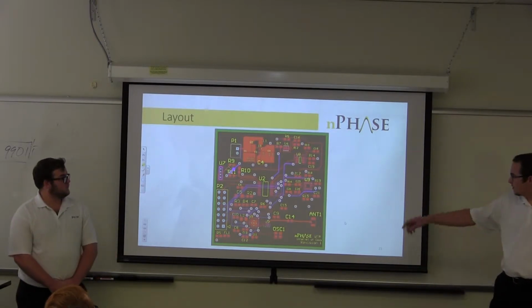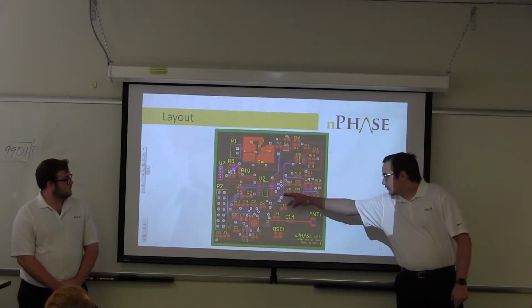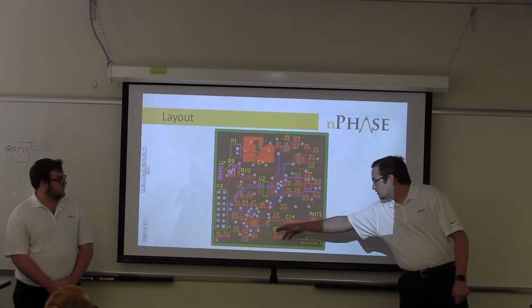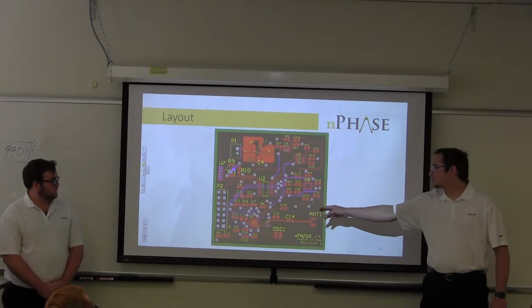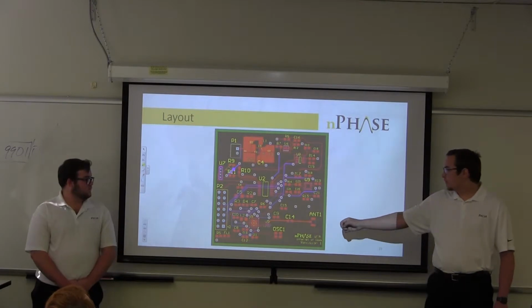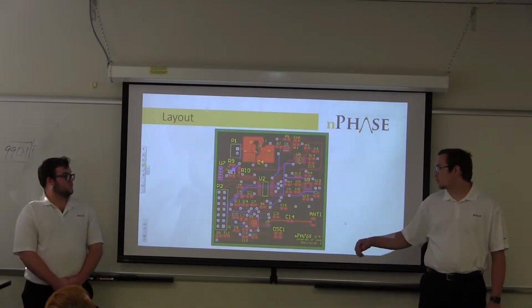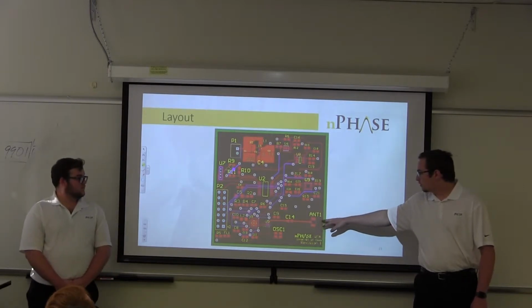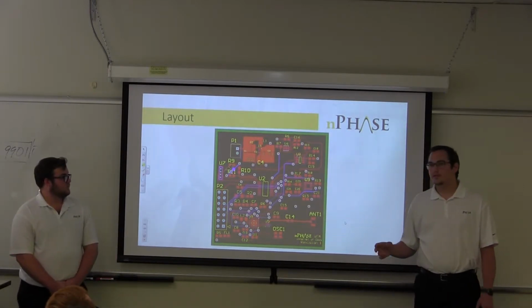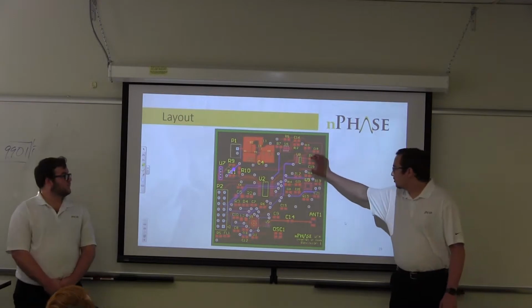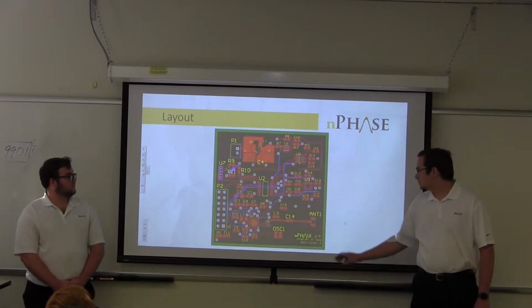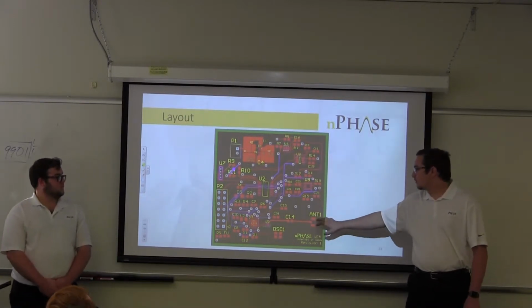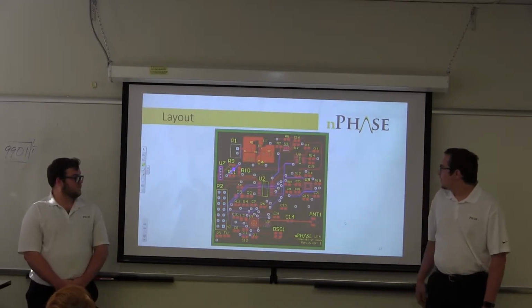And then U2 is our MSP430. This is our 1310, which goes through the balun, which is quite small, which needs these ground pads around it so that it matches the impedance properly. Then it goes into a 50 ohm trace, which is 17 mils, over to our antenna. We have two different power planes. This section right here is 3.0 volts. The rest of it is 3.3, and then there's no power plane below the antenna.